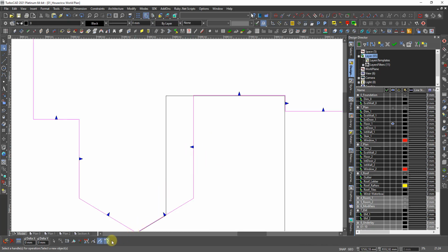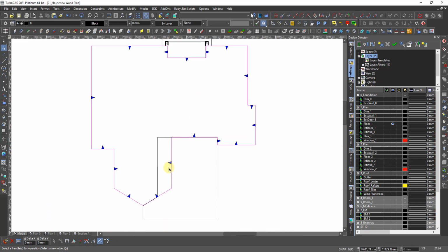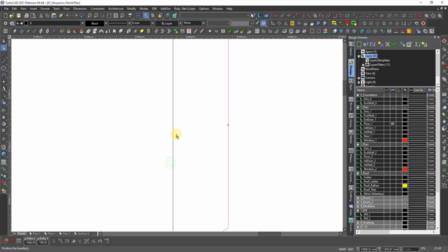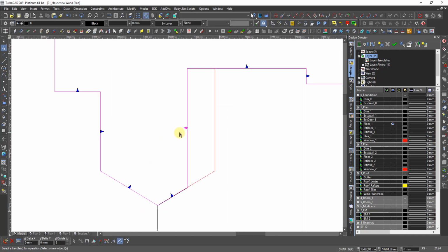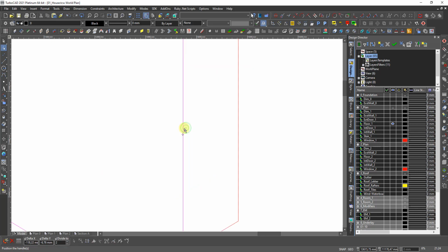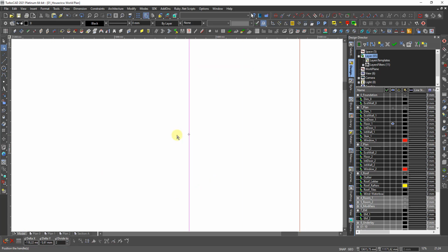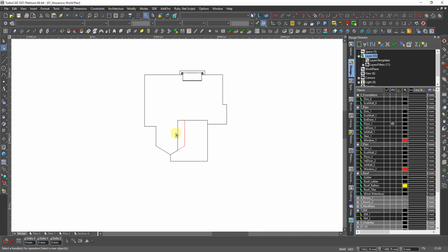And the push mode should be off. It should go there, and it should go 12 millimeter inside that edge. Then I go to J. That's inside, and then I go 12 millimeter inside. That will be minus 12 and 0 and enter. There we have it.